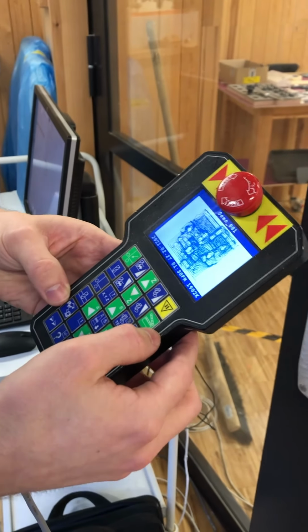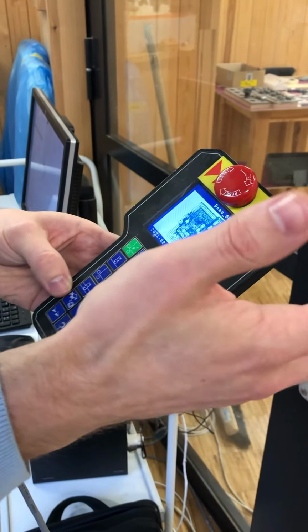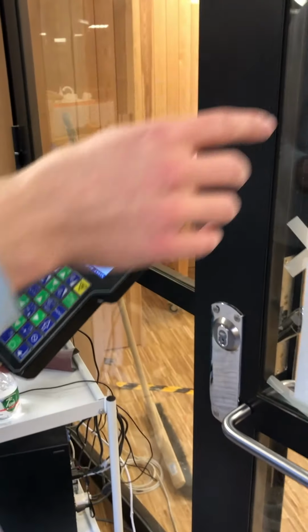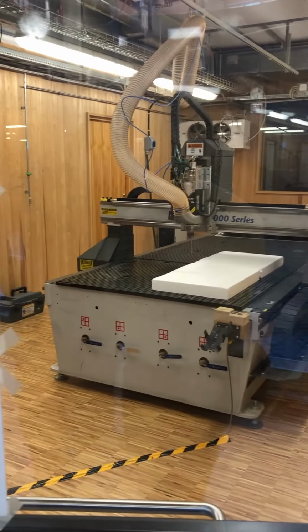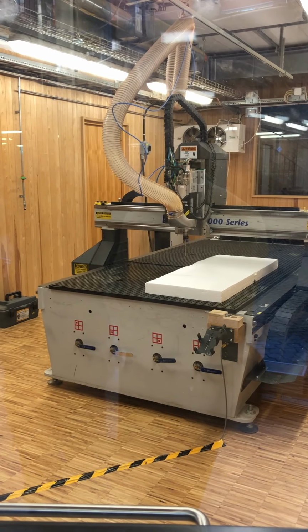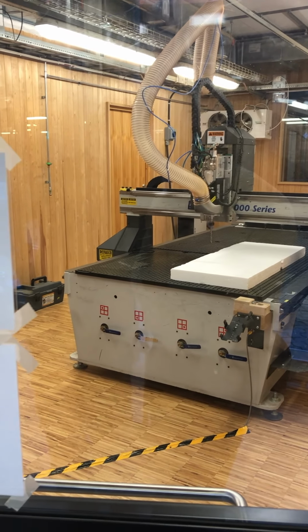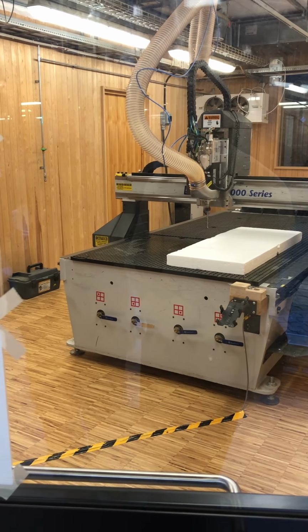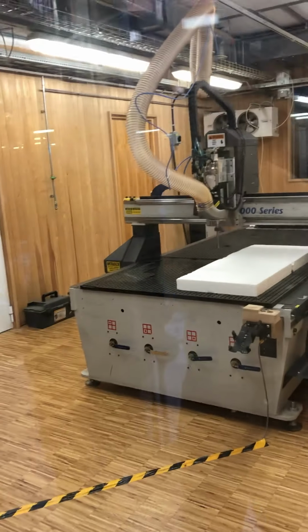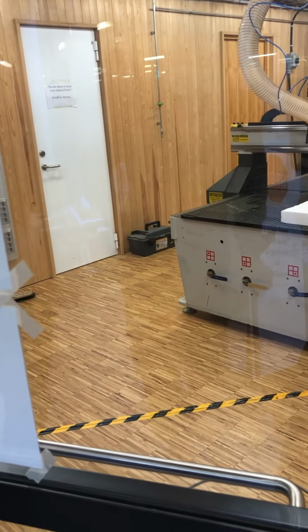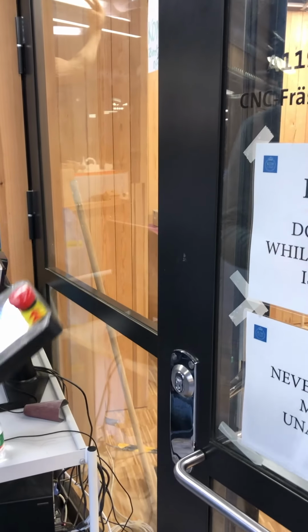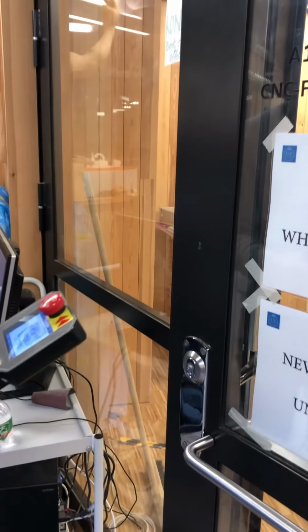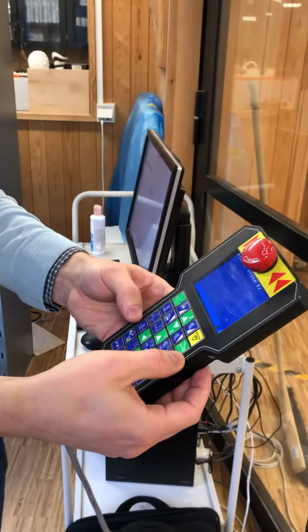And I might not have stressed that enough, or put enough emphasis on it. But you have to, of course, make sure that the actual point on the stock which you now use as a soft home has the same orientation as the stock point in Fusion 360. It might be obvious, but it's really important so that it doesn't start one whole unit off. All right, then we're ready to execute this.